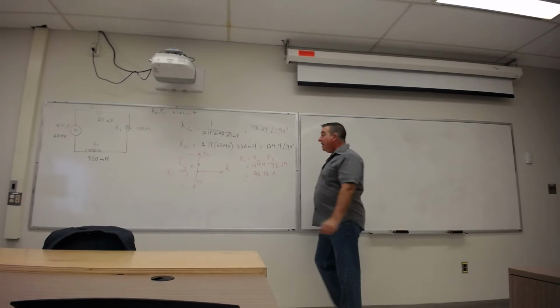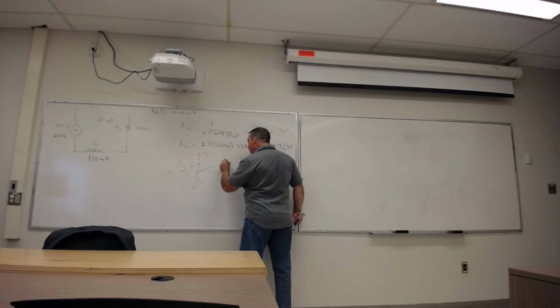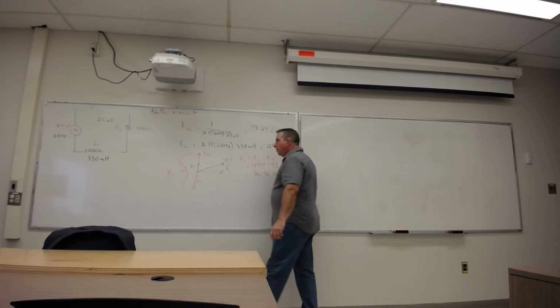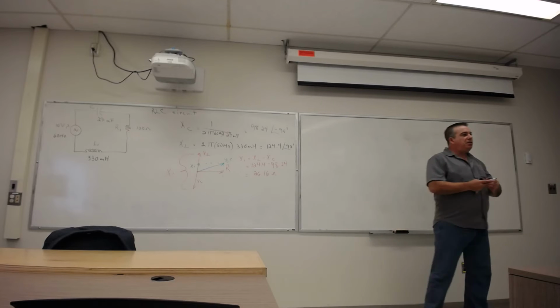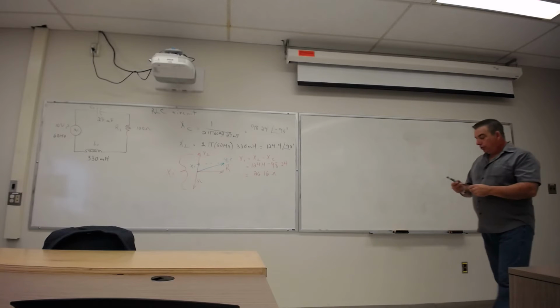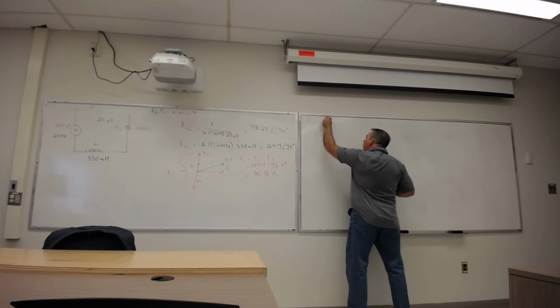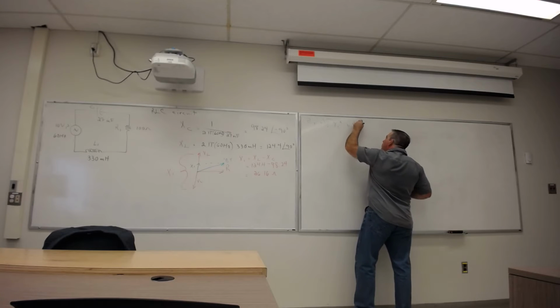So that means our impedance is going to be the sum of R and X1. So our impedance, this vector right here, Z total, is actually going to be the vectorial sum of X1 and R. All right? So if we work that out, Z total is the square root of X1 squared plus R squared.